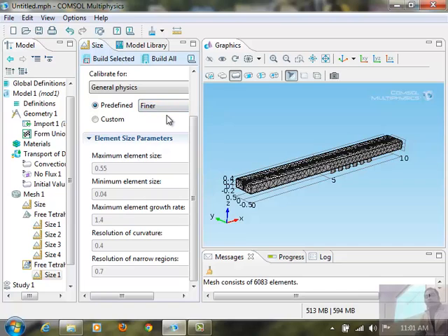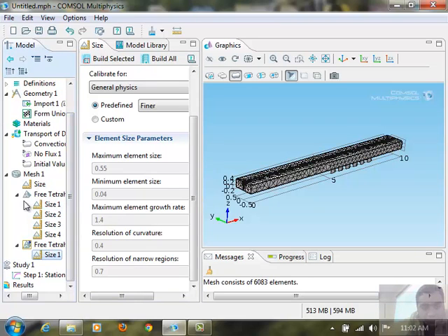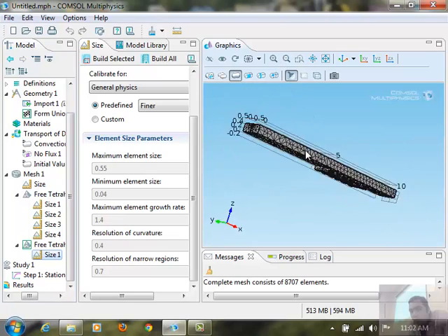So with this we have seen how to do it domain wise, like selecting a domain, refining it, choosing a different domain, giving different mesh settings. Now how do we implement mapped mesh in this case? Because now we have these different edges and the faces are not forming exactly a cube, like 4 edges required for mapped mesh. So let us just, for completeness, I generated this. So now the full domain is generated, but now let's try the same example with mapped mesh quickly.